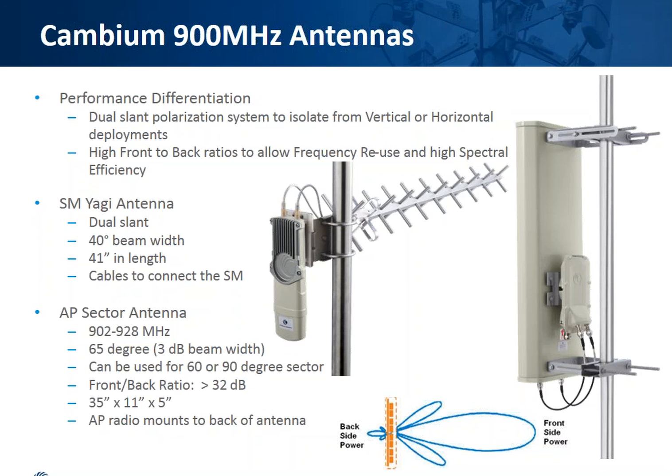Okay, another question that came in: are there any plans for a 17 dBi antenna? Not at this time. The propagation characteristics of the 900 product are pretty good, so you do get extended distance and range even with these 12 and 13 dBi antennas. With a 17 dBi antenna, you're talking about 6.5 feet long in terms of the Yagi, and so we haven't explored that just yet. If there is a strong demand for that, we certainly could consider it.